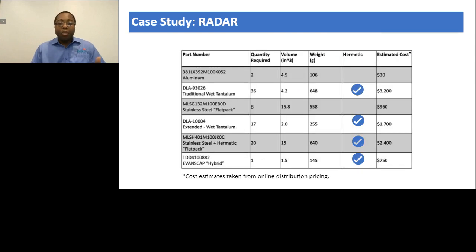Again, on this slide, we see a summary of our options. Aside from the obvious design considerations as we have discussed, we actually see that some of these solutions require multiple capacitors that will impact assembly costs and affect overall system reliability. In addition, a capacitor's small size and weight will allow a designer to put energy storage closer to the emitter, reducing the need for additional wiring. Nonetheless, asking ourselves the right questions as we compare our options helps ensure we've chosen the best capacitor for our application.